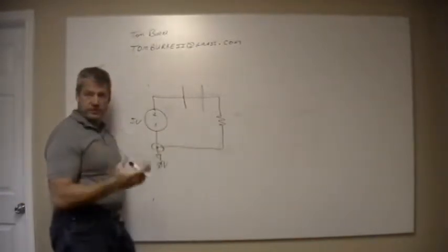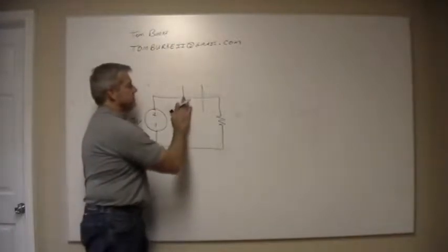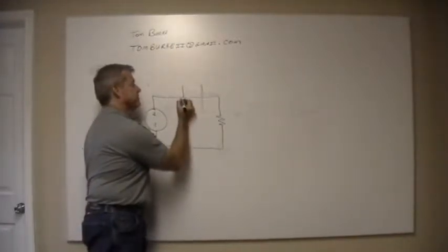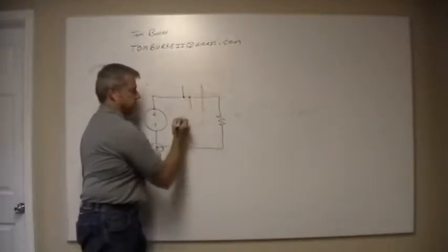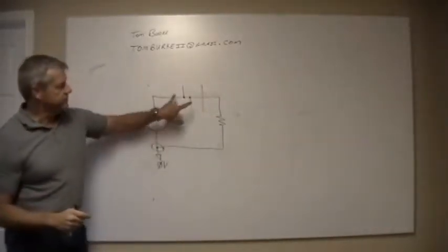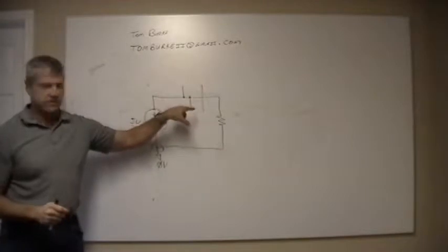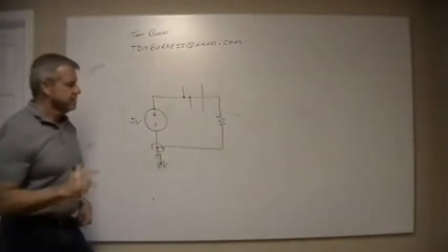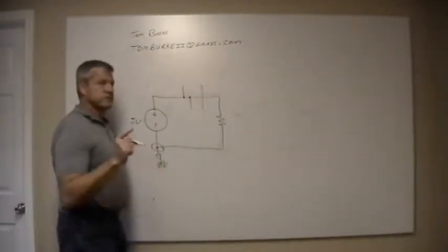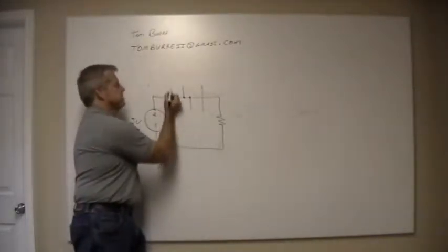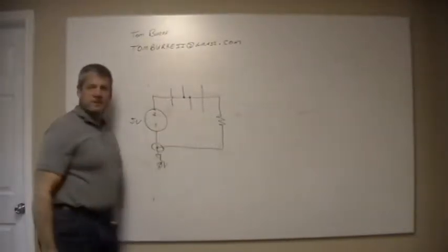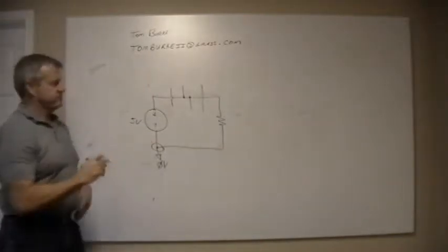So you can create confusion. Convention, which not everybody follows, is to do this so that you know that these connect to this circuit and that one doesn't. You don't see it so much anymore, but in old stuff you'll see the loop. It jumps over it. It's not connected.